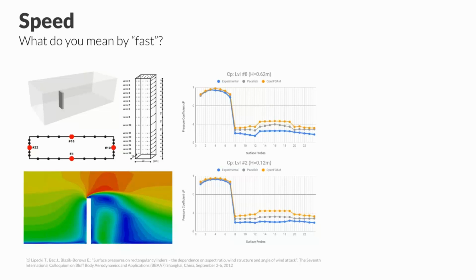How fast it is and whether or not it outperforms another method is, as always, dependent on the specific project, depending on the specific physics. There's no one size fits all. But we wanted to give an indication of the speedups we've seen for these specific projects, right? The applications where we've seen success are where a transient aerodynamics phenomenon shall be predicted, and this is oftentimes vortex shedding on slender structures. And here is an example.